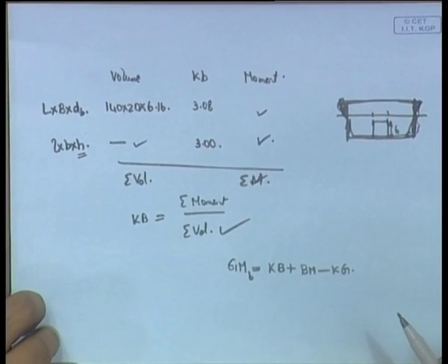See, the thing is, we had a formula KM minus KG equal to GM. You have a problem calculating the KM for such a bilged condition, because this is not an ordinary kind of ship. First of all, it's not an ordinary box shape vessel. It's a box shape vessel in which you have lost some volume, and it's not even lost up to the waterline. So, that direct formula of KM is equal to D by 2 plus B square by 12 D cannot be used here. That is why we had to find it.